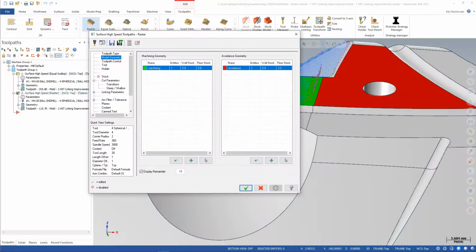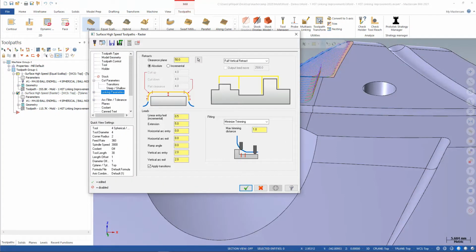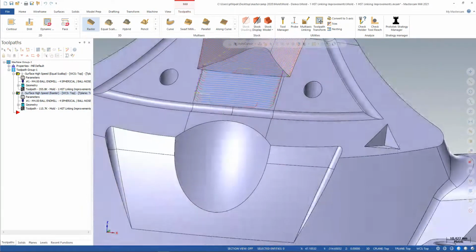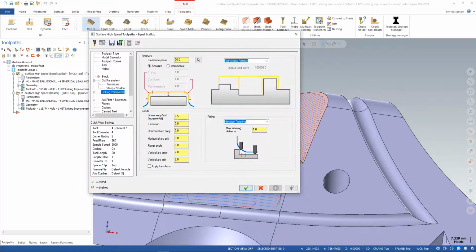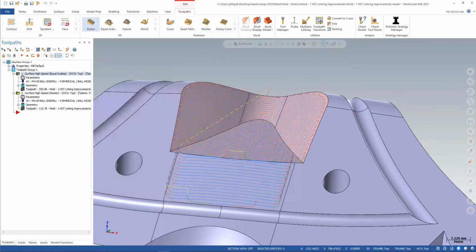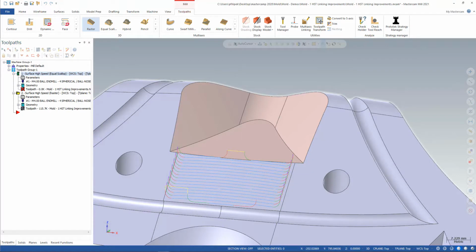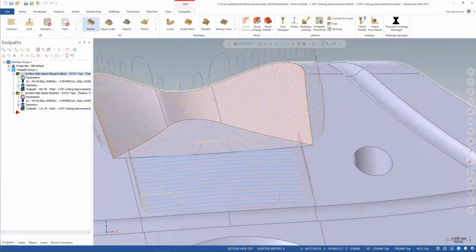So make sure you're taking a look at that in the linking parameters page. If I come back to this top surface, I can fix this one back up to apply transitions again. And I'm going to extend this one out 3 millimeters. Now if I green check out of there, see how it extends these surfaces out also. So that can be handy for some people too.